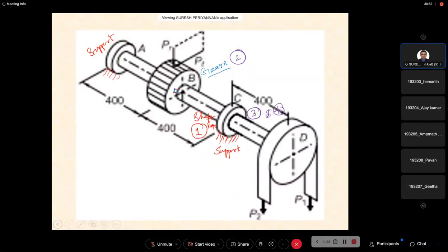Now that is journal bearing and roller bearing. I mean ball bearing or rolling bearing, same. Ball bearing and rolling bearing are under anti-friction bearing. That's what we discussed in the third chapter, and we discussed Petroff's equation and Stribeck's equation for bearing design. Okay, right?